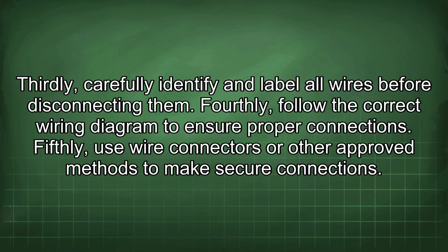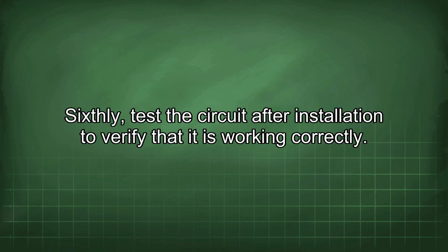Fourthly, follow the correct wiring diagram to ensure proper connections. Fifthly, use wire connectors or other approved methods to make secure connections. Sixthly, test the circuit after installation to verify that it is working correctly.